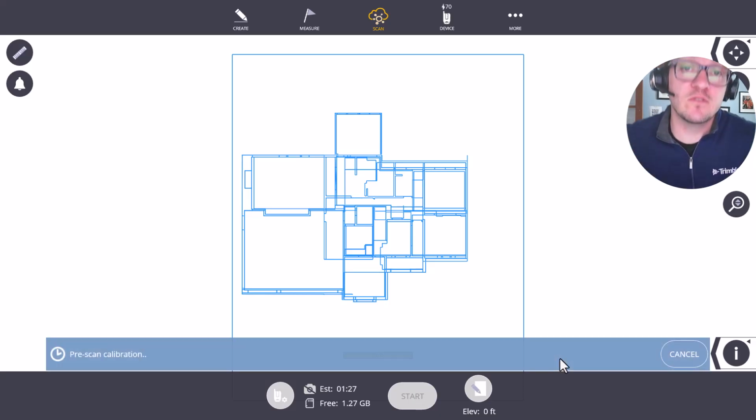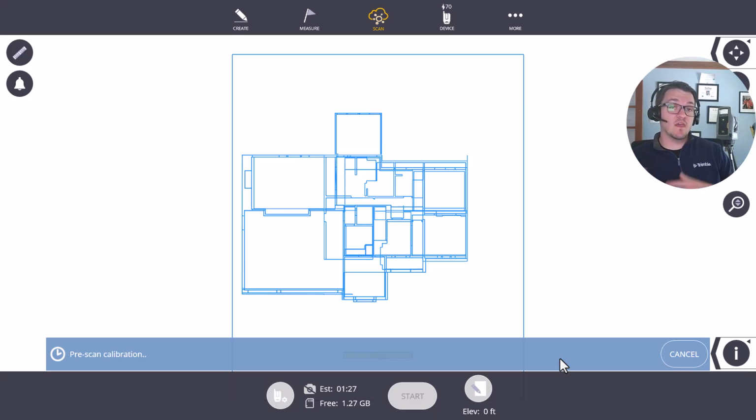Now, I'm going to start a scan. I could set the elevation of a scanner by just doing a resection or measuring two grid lines. If they have elevation, obviously the first scan would be placed to that elevation and to those control points in X and Y as well. But for a lot of floor analysis, it's easier if you only have a reference elevation to hit, and we can do that just with the scanner a couple different ways.